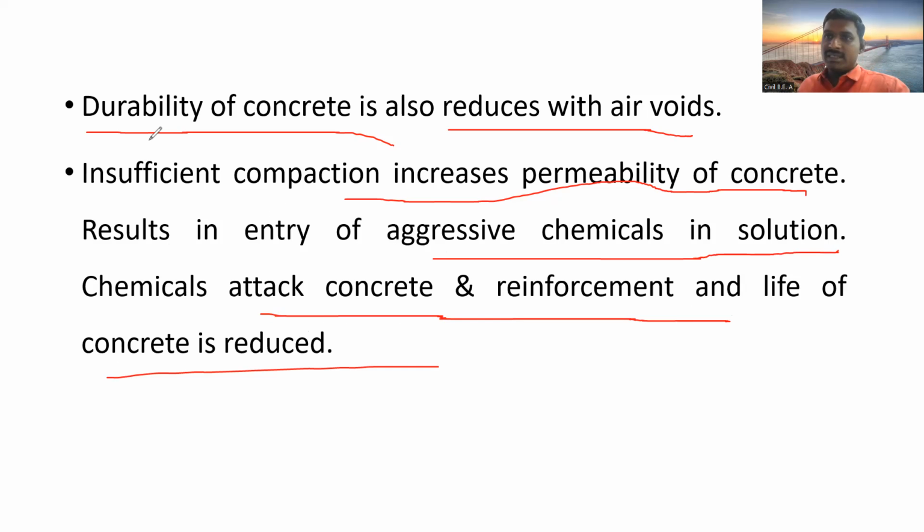So the air content we have to remove by compaction, which is very important. If we concentrate on compaction, all the other properties of concrete, such as permeability, strength, and durability, will improve when we use a proper compaction process.